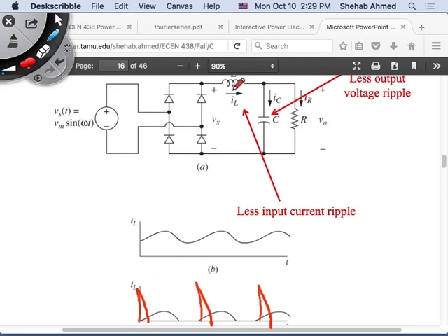But now, if I put this inductor here, the inductors don't allow very large variation in current. The time rate of current change has to be reduced if I put an inductor. So I end up with the current waveforms looking like this. This will deliver similar area under the curve, so similar power will be delivered to the load, but with a much lower peak value of current. So it's better for you because you buy a lower switch rating for equipment rating. You typically buy devices, circuit breakers, cables, etc., based on average current rating as well as peak. You have to consider both, right? So here you'll be able to buy cheaper equipment, basically.